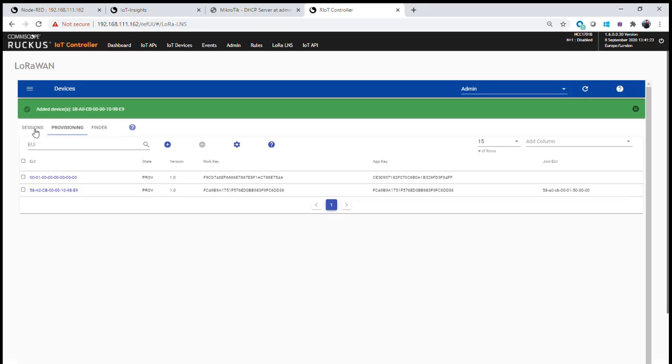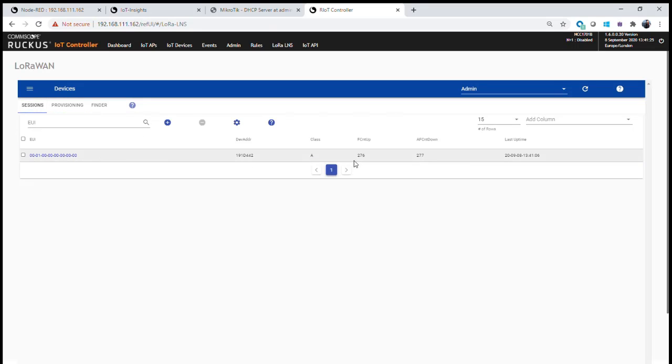So during this time, it's a good opportunity now to put the battery into the device, into the sensor, and allow the device to boot up. Now when it boots up, the first thing it'll do is reach out on a predefined frequency and channel and look for any LoRa network servers or any LoRa network gateways that are out there in the network.